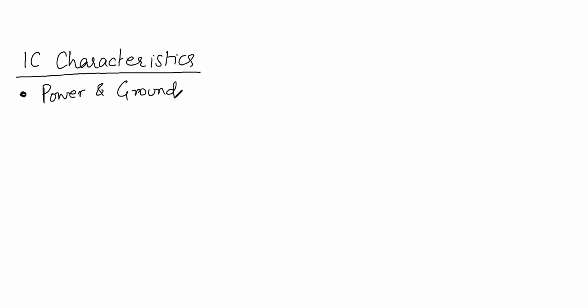But you have voltage dropout circuits which convert your power supply from one value to another, and it's easier to lower the value, so you can bring it down to 3. So you need an LDO before that chip to drop down the power.